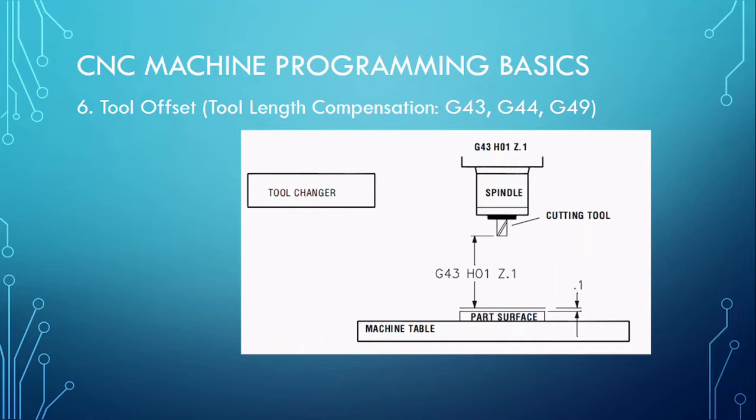One thing to be very noted here: the tool length compensation or the cutter compensation, whenever they are used and are no longer to be used in the same parts program, they must be cancelled, else the tool will begin to misbehave. So once you are done using a compensation, it has to be cancelled before any other line of code is written. So that's another very important point to note.